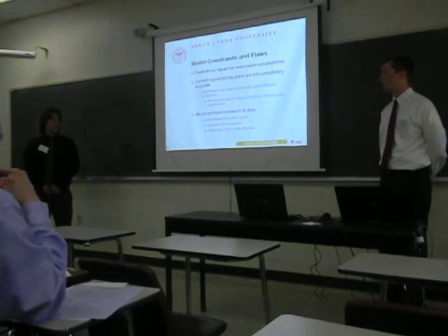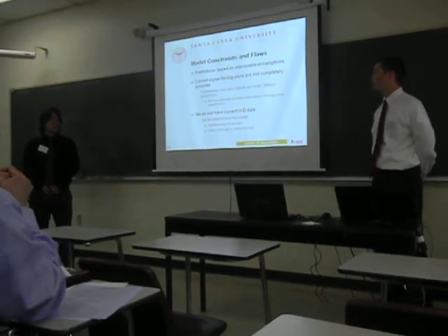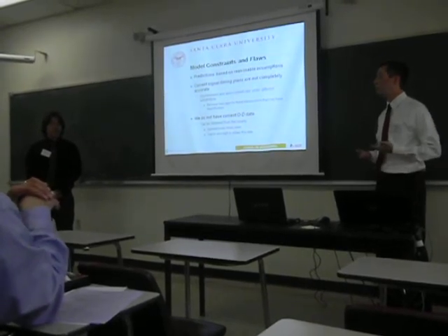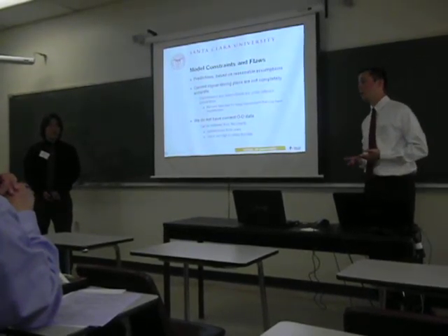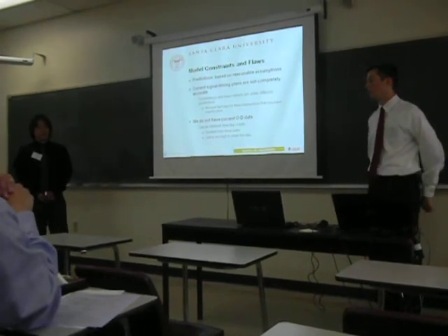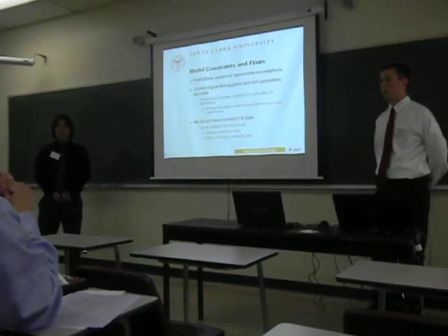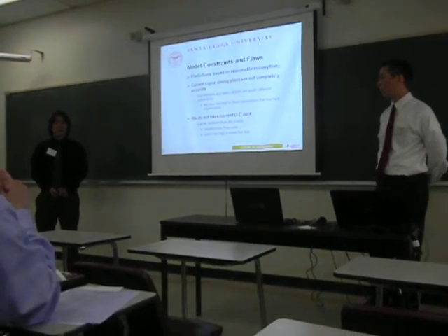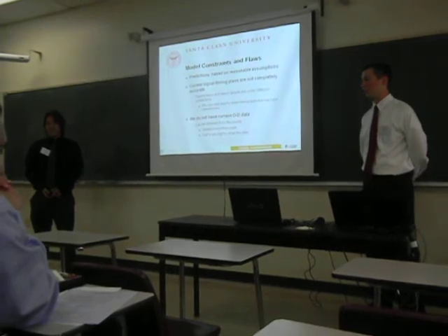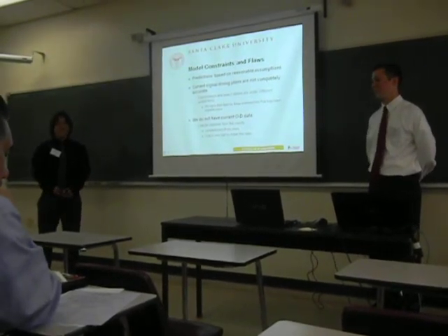As far as the current signal timing plans, we've gotten what we could from the city, but it could still be improved and updated. Also, same with OD data. Like I said earlier, we have an old OD table. It's something that can be obtained from the county. They update it every 3 years or so, but the cost to get those numbers is a lot, and we don't have that kind of budget.